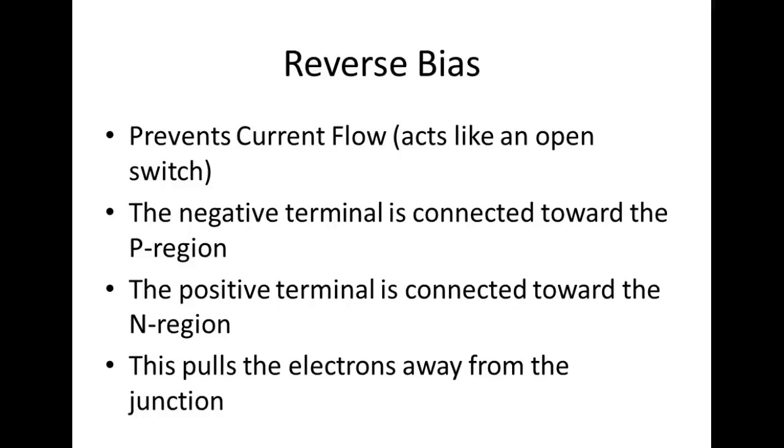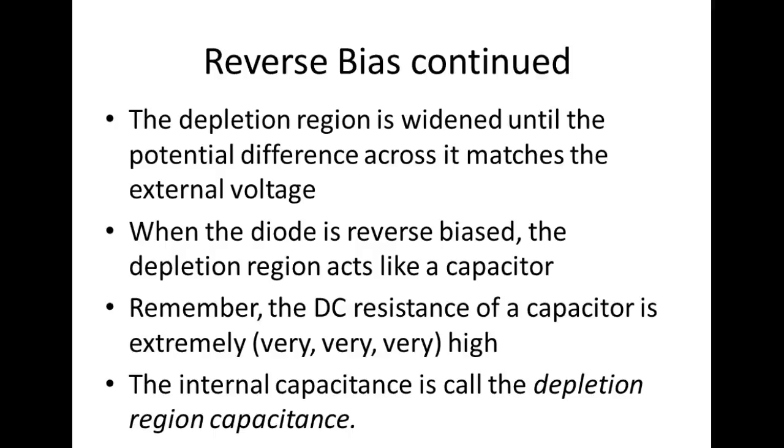It's going to burn up. So we need to make sure we stay below the breakover voltage for the diode that we've selected. So that's one of the parameters on the diode. It's not only how much forward current it allows, the maximum current it allows, it's also over what voltage it will probably break over at if you exceed it.